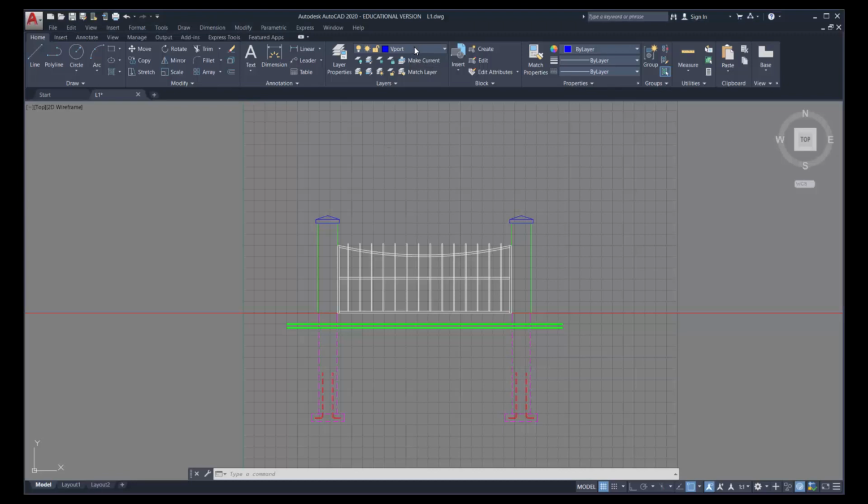I'm first going to switch from the viewport layer to the DIM 24 layer. I'm going to go into annotation to make sure my dimension is using the DIM 24 style. This number and that number should be the same. We always start with a linear dimension. So you can see in the menu here, it says linear.